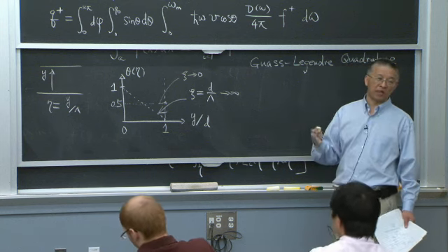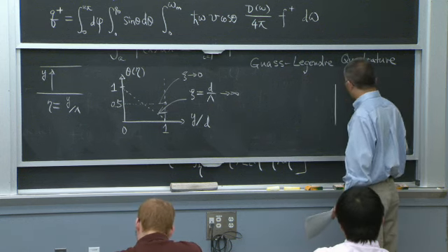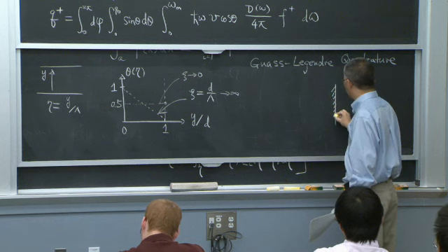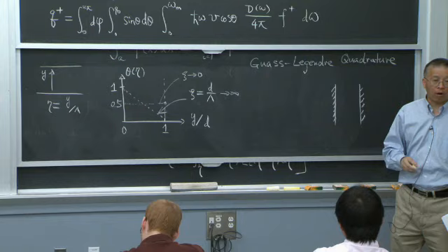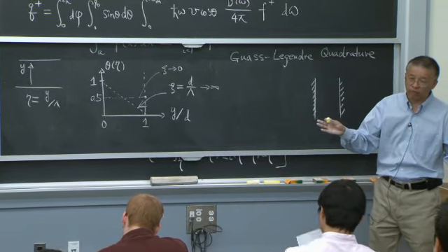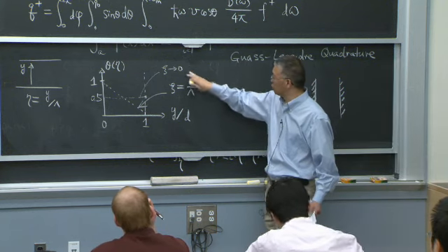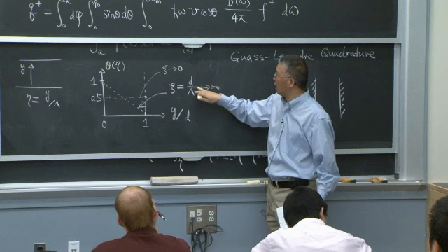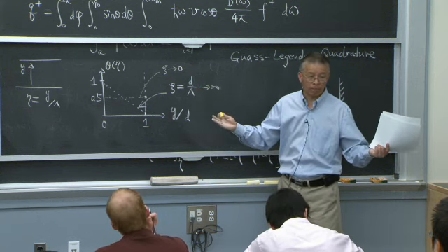So let me take the example I talked about before. This is the case when I have radiation transfer between two parallel plates in vacuum. Right? There's no scattering inside for photon because xi goes to 0. That means d is very small compared to mean free path. There's no internal scattering.